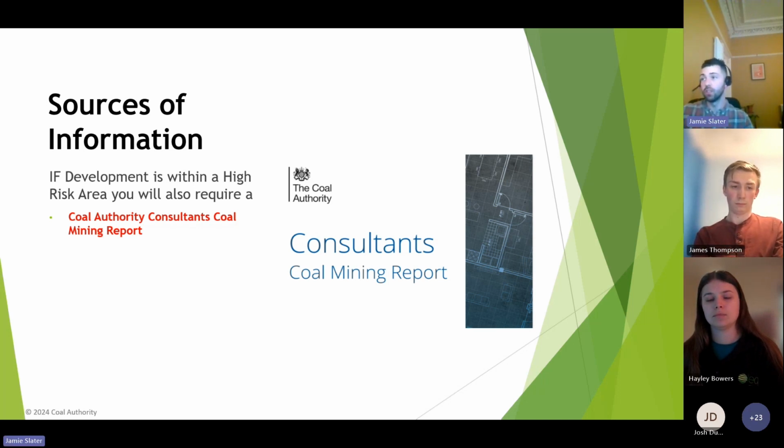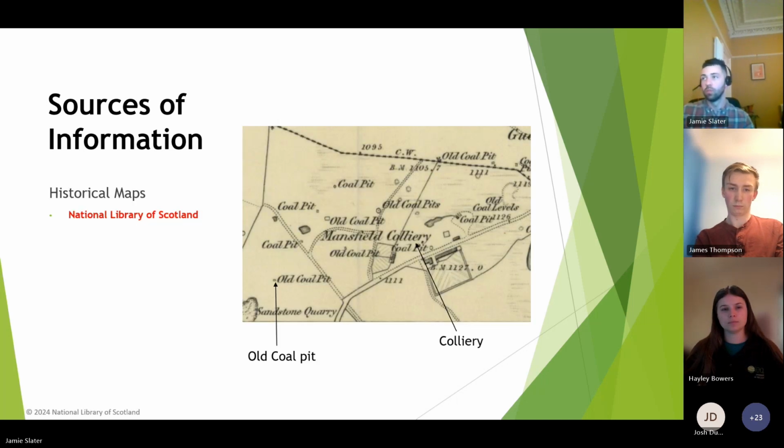Section 2 goes on to outline any site investigations that have been undertaken, any remediated sites, any coal mining subsidence, including mine gas or mine water treatment sources. More importantly, you should also be looking at past mapping. So the National Library of Scotland Maps have a collection of historical mapping available in Scotland. You've just got to make sure you've got the appropriate licenses for commercial reuse.